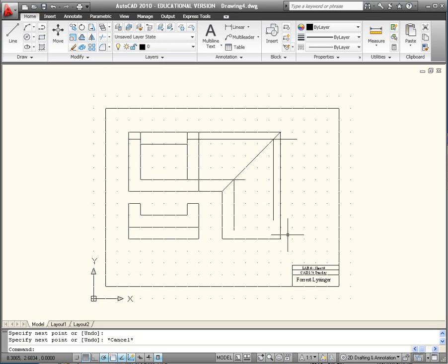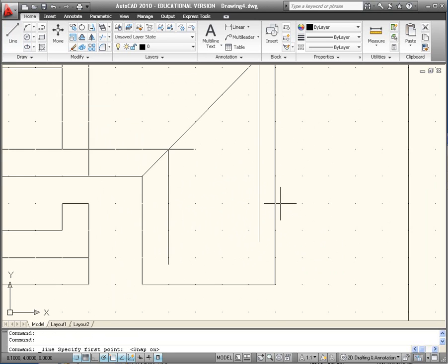Okay, down in this view we have a 1.5 inch dimension here, so if I turn my grid snap back on and go from right there to right there, and I can bring a line over from here to this point and then come up to locate my angled face.